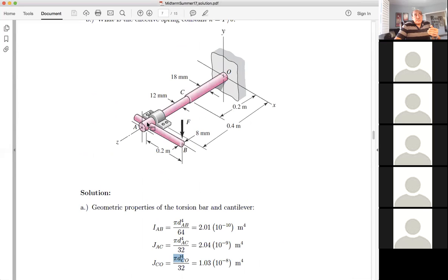When I do that, I have to be careful where I put the coordinate system. For example, if I put the coordinate system at A, then for the force here, I have to consider one generic point moving along here, so x is here. Then the moment is going to be a function of 0.2 minus x. So the moment would be F times 0.2 minus x. And then we take the derivative, which would be 0.2 minus x, and it's going to take a lot more calculations.